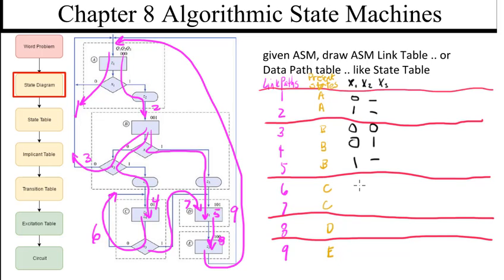All right. Now in link path 6 and 7, we're looking at X3, which has a value of 0 and 1. We're not looking at X1 or X2. We're not looking at X3 up here. And then in algorithmic states D and E, we're not looking at any of them. Now, just because we're not looking at them, that means we've got to block them out. We've got to tie X1 into this state. Okay, so now let's document the next states.